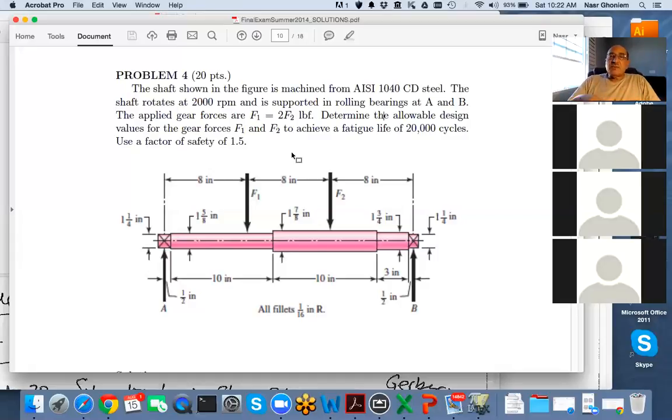Also, additionally, if we are interested in fatigue, let's say at the shoulder, then we would need to figure out if there are stress concentrations there. So the issue of stress concentration would be of importance. And then if I go to stress concentration, it raises the question: is the stress concentration factor in fatigue the same as the stress concentration factor in tensile or uniform steady loading?